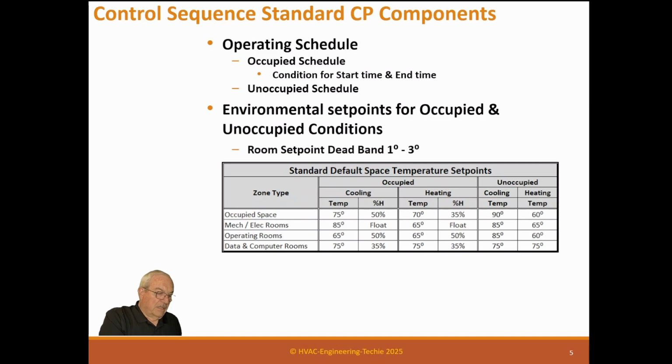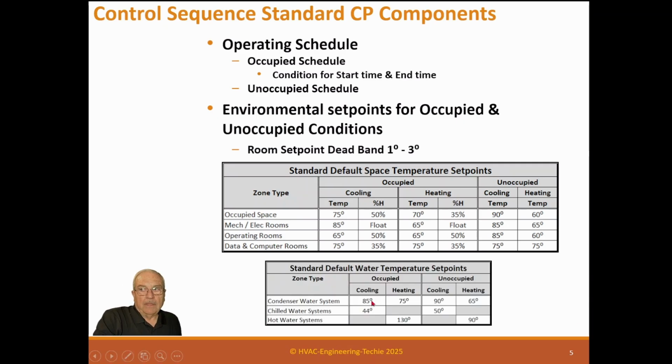The data people used to tell us that the chip processor needs cold air. We'd like to have 68 degrees. We'll settle for 72, but we'd really like to have 68 to get them to run better. But in recent years, they discovered that those things run good at 95. They don't need 68 degree air. So nowadays, we're able to pump 75, 78 degree air into the room, make the people comfortable, and the processor still will run below 95.